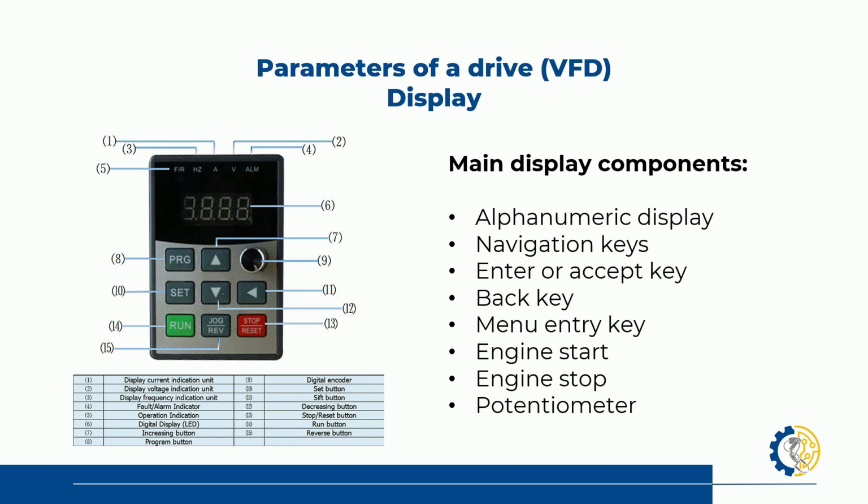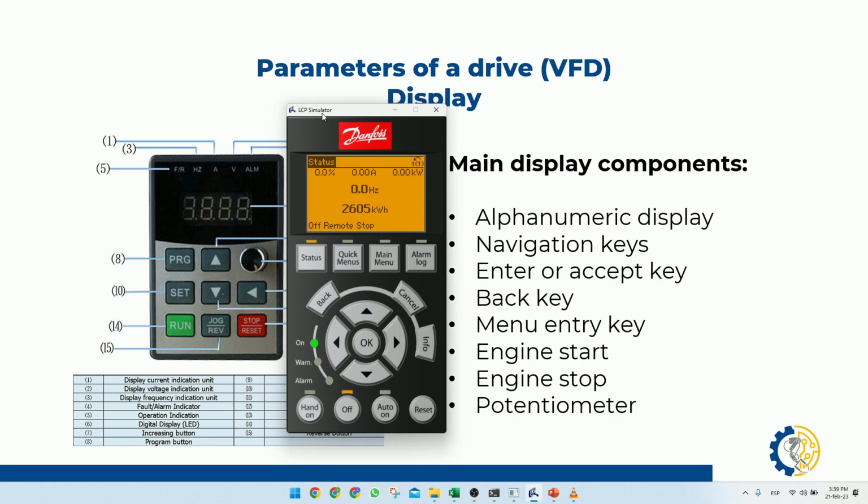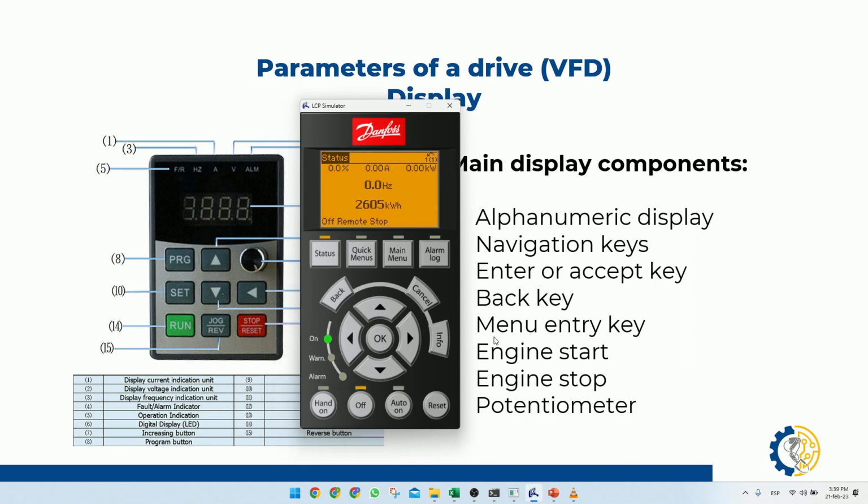For whenever the operator needs something very quickly to jog the machine or to move the machine. That's why it has two speeds. One, it has the minimum and maximum speed, but we can control our speed manually through our potentiometer. And here on this side we have our Danfoss drive, but it doesn't have that potentiometer. So how else are we going to control our speed?